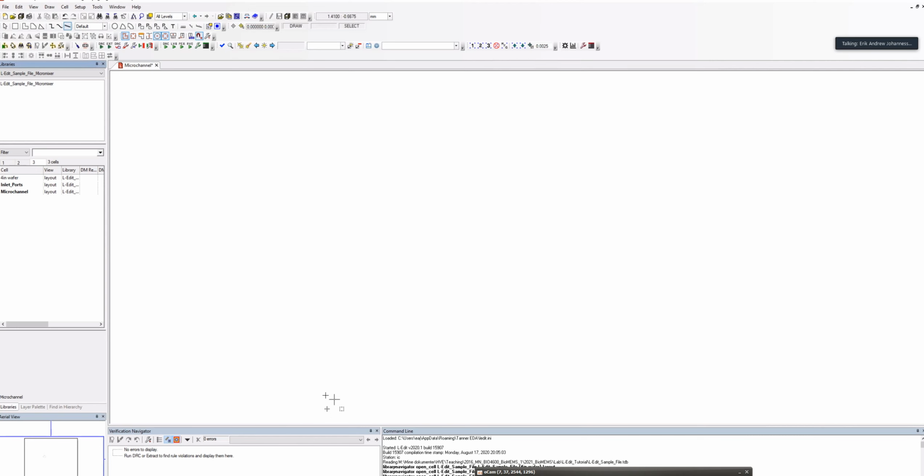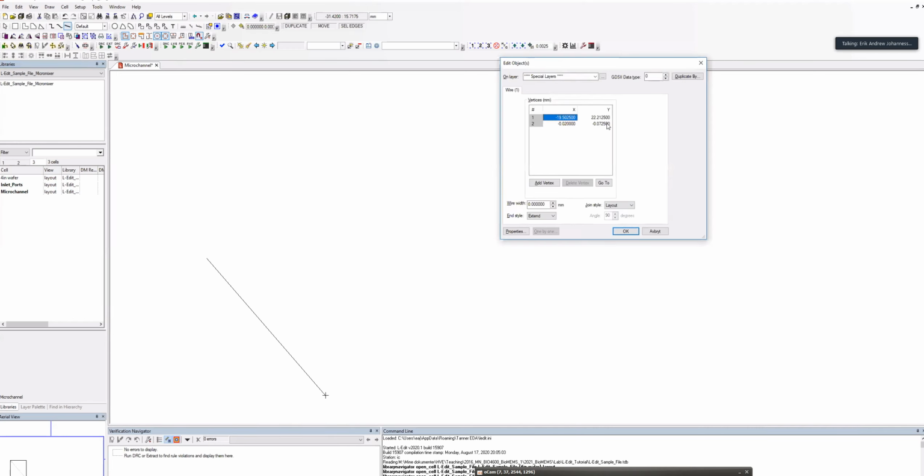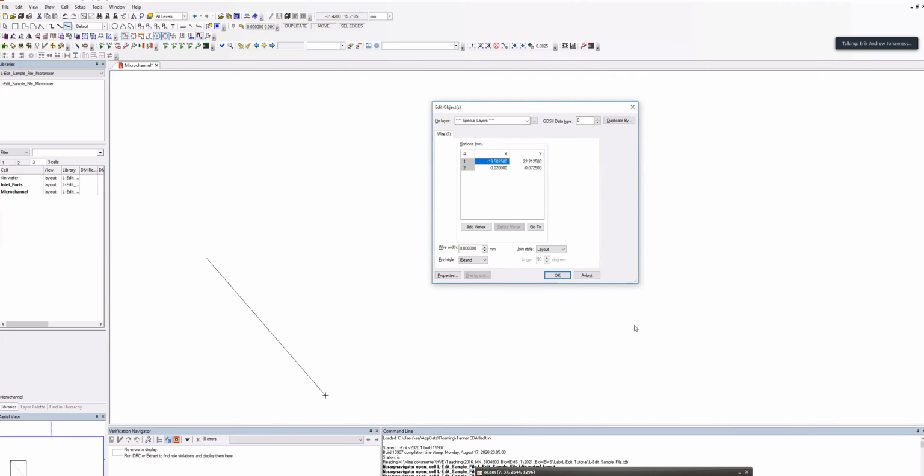Again, we had the center point down here, and I always like to use the center as a reference. If you like the wire to start from this point, you simply click, and you have a wire coming from the cursor as in any drawing program. The question is how long and at which angle it's going to be. I don't really care. I just double click, and that's my wire. I go back into Control E again, and now we have a slightly different window than with the circle, because it's a wire, you have x and y coordinates and so on.